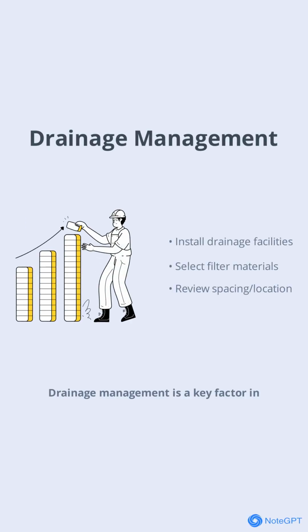Drainage management is a key factor in maintaining the stability of rock fill structures. This involves not only installing drainage facilities, but also carefully selecting the materials for filter layers and ensuring proper construction. The location and spacing of drainage facilities should be reviewed and adjusted as needed to suit site conditions. Effective drainage management prevents water accumulation and reduces the risk of structural failure.